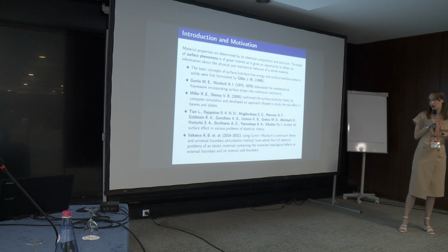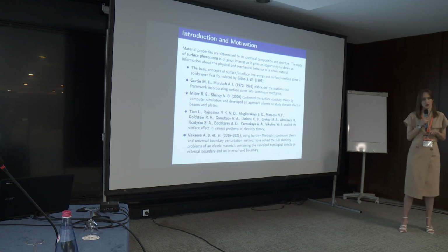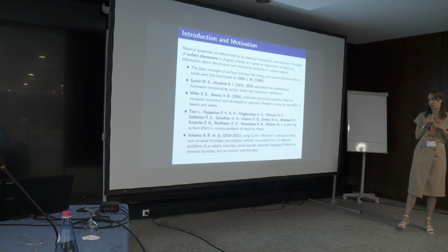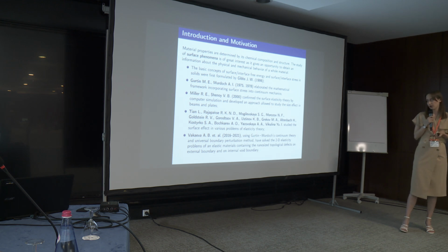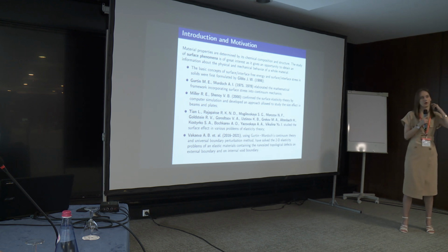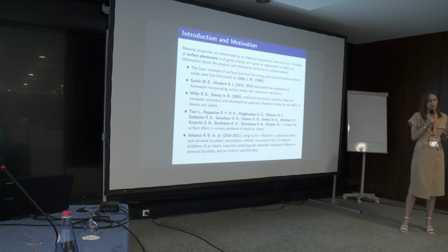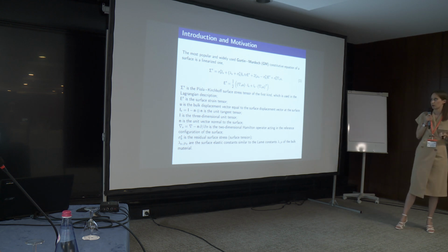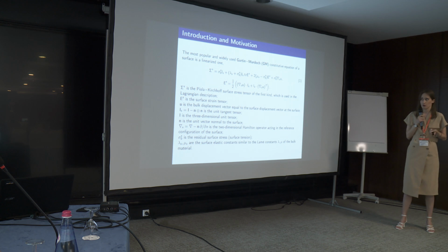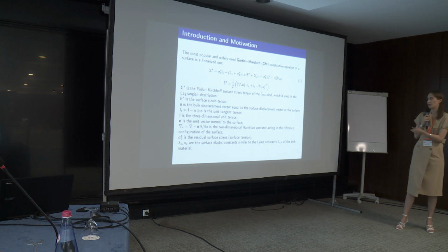For example, our scientific group also used this simplification of this theoretical surface model, and we have results for 2D problems with nano defects such as holes or inclusions with an arbitrary boundary. So, the most popular and widely used Gurtin-Murdoch constitutive equation of the surface is linearized by Formula 1.